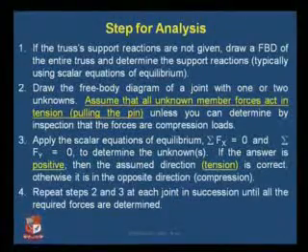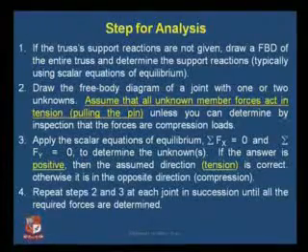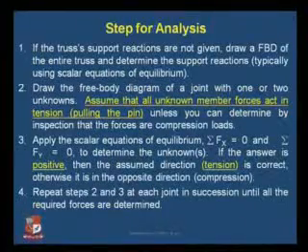Then once you have solved one of the joints, you have to repeat the same points, that is point number 2 and 3, to each and every joint where you have a maximum of 2 unknown forces.